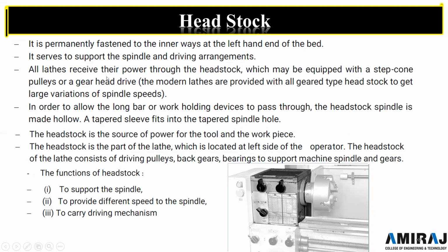जो भी सारे के सारे लेथ्स हैं वो कहाँ से पावर उनको मिलेगी? थ्रू हेडस्टॉक। और उसके अंदर या तो पुली टाइप अरेंजमेंट होगी, जिसमें स्टेप्ड वे में पुलीज होगी, या तो फिर गियरिंग हेड। जो भी मॉडर्न लेथ्स हैं उनके अंदर गियर टाइप हेड स्टॉक ही यूज होगा विथ लार्ज वेरिएशन ऑफ स्पिंडल स्पीड्स। गियर टाइप अरेंजमेंट का बेनिफिट ये है कि नंबर ऑफ स्पीड्स जो पॉसिबल मिलेगी वो इंक्रीज हो जाएगी। सो दैट इज द बेनिफिट ऑफ गियर टाइप हेडस्टॉक।